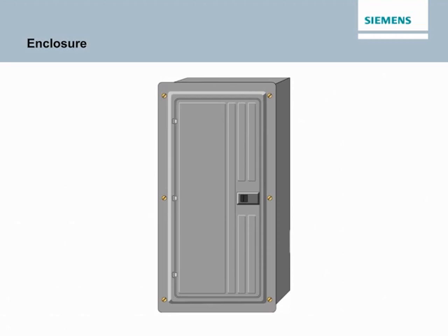The National Electrical Manufacturers Association, or NEMA, has established standards for electrical equipment enclosures. NEMA Type 1 enclosures are intended for indoor use. NEMA Type 3R enclosures are intended for outdoor use, primarily to provide a degree of protection against rain, sleet, and damage from external ice formation. Load center enclosures typically conform to one of these NEMA enclosure types.